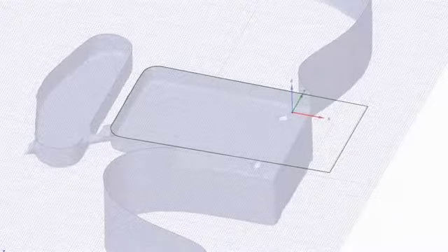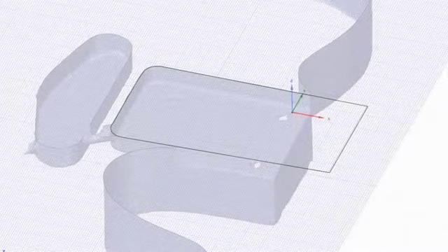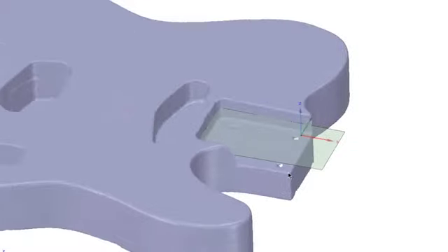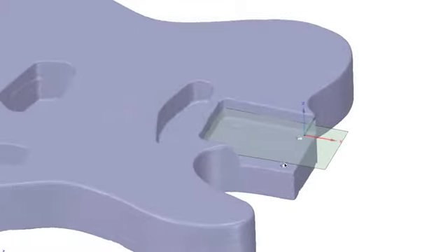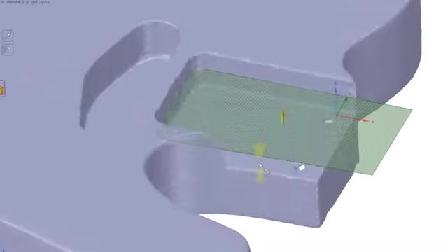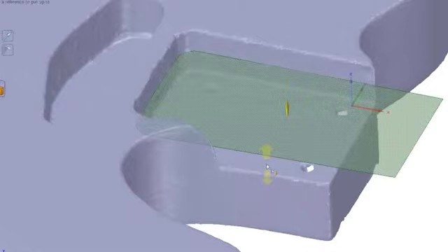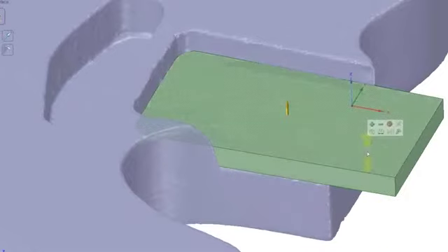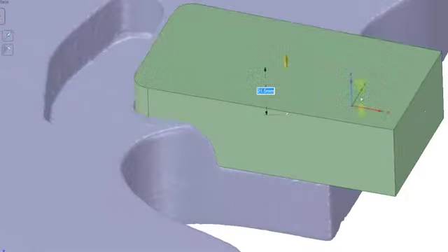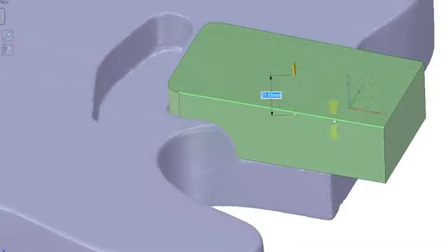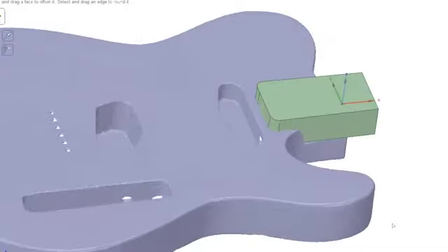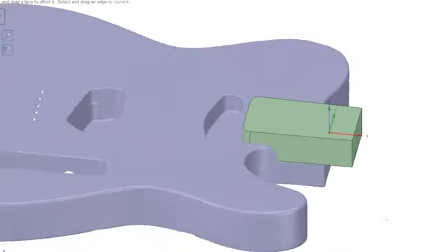And all I need to do is go back over to 3D mode. And a nice thing about the way SpaceClaim works is any bounded sketch automatically gets converted into a surface. So I can immediately come over and grab the pull tool and say I want to pull this up to, and click on the mesh itself, and it'll extrude that pocket up to the top of the mesh. So you can see that I've created a block where that neck is going to fit.